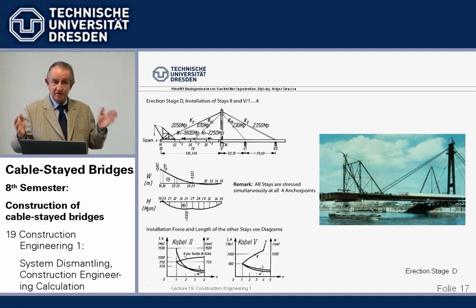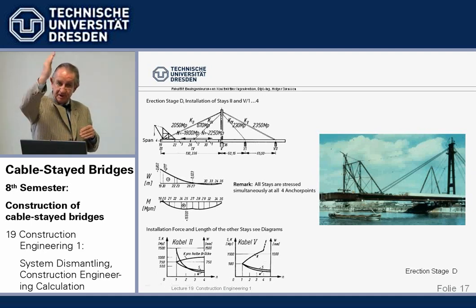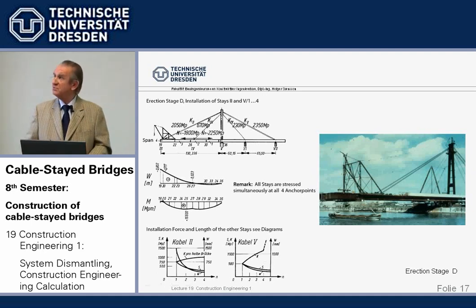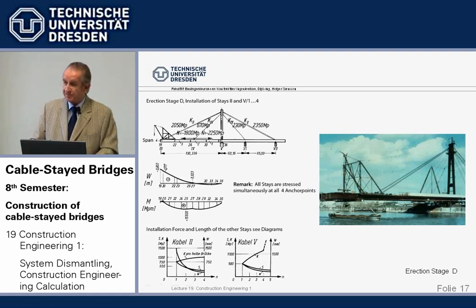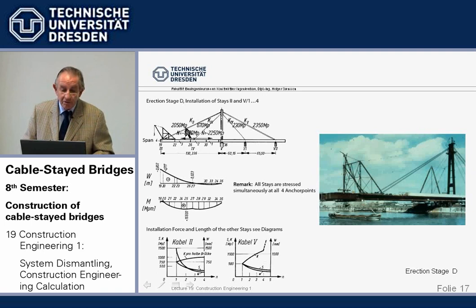So if we have large cable distances and a flexible steel beam and concrete, that will all be reduced. Then we can have this here, 2.5 meters going up and down, which is considerable. I mean, that's more than the top of the door. And it's a substantial beam. Well, we have substantial forces there. And now we know we have these cable forces in here. And we have, of course, the backstay, corresponding to this forestay. We must anchor the force back here into the pier.